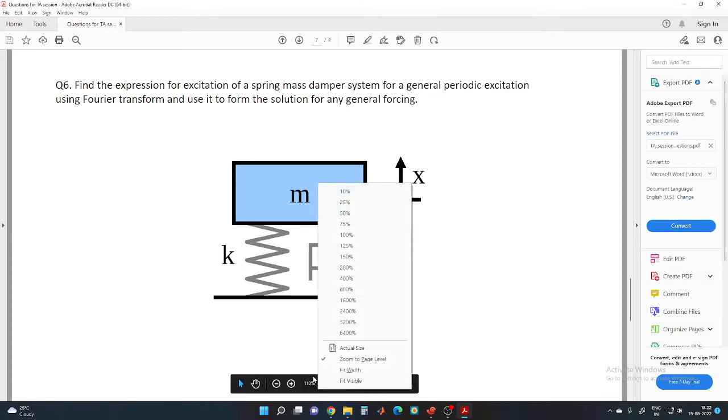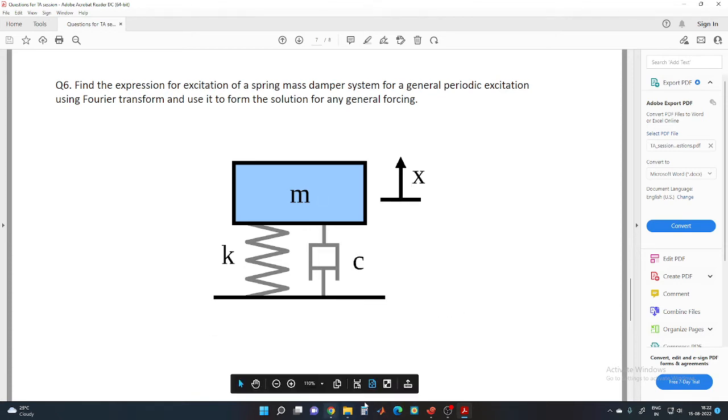Like if we remember the class lectures or the usual solution approach, what we usually have is we usually find the solution for M, K, and C. If we assume X in this direction and F in this direction, what we assume is F is of the form F naught e raised to power j omega t, or basically it has only one frequency component, and that also of a sinusoidal form.